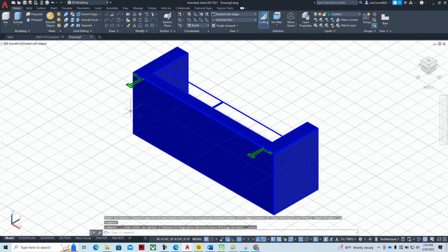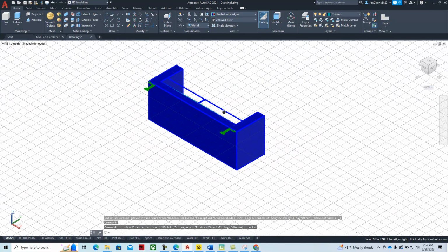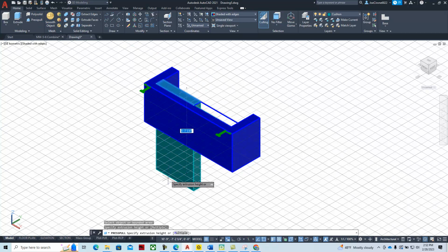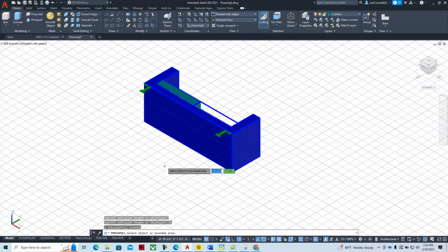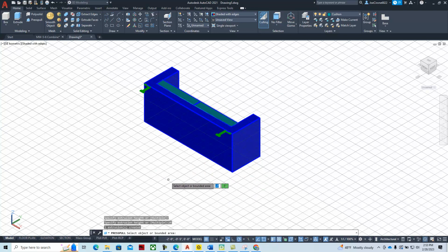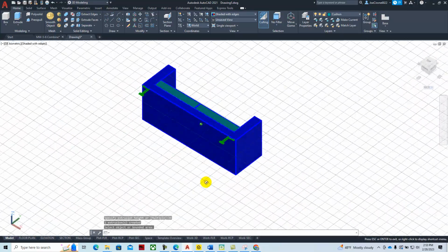is we're going to 3D rotate this. Well, we can put the cushions in first, and we'll make those cushions 30 minus 6, so we'll make those 24. So we'll say press pull, we'll hover, and we'll push this down 24. We'll do it again, 24, and then what we'll do is 3D rotate this.